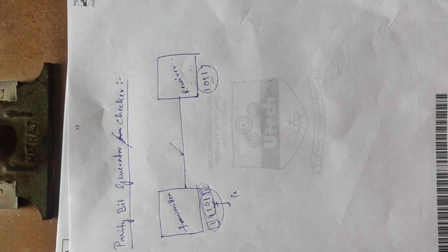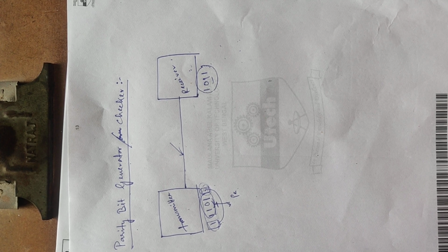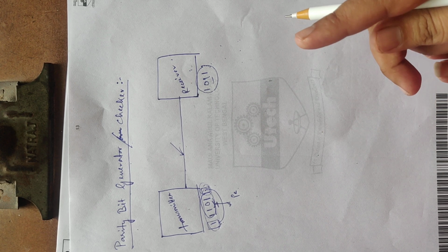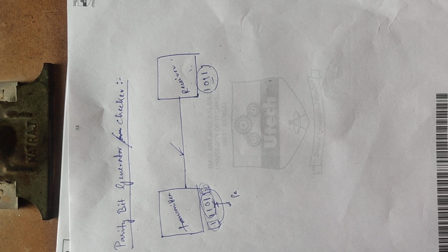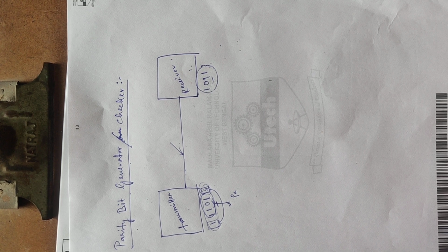In order to check or generate the proper parity bit in a given code word, the basic principle used is that the modulo sum of an even number of 1s is always a 0 and the modulo sum of an odd number of 1s is always a 1. Therefore, in order to check for an error, all the bits in the received word are added. If the modulo sum is 0 for an odd parity system or 1 for an even parity system, an error is detected. So to generate an even parity bit, 4 data bits are added using 3 XOR gates.